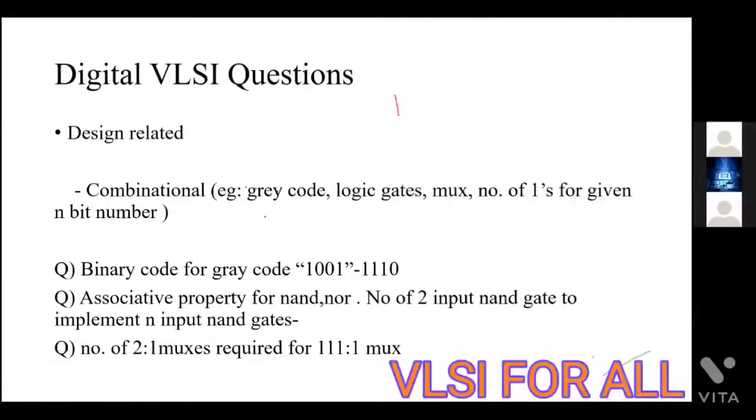So for NAND gate implementation, these are the 3 inputs. The circuit which I have drawn is for the 3 input AND gate using the 2 input AND gate. So here the associativity property holds, and because of that, you are able to implement the things without any additional excess gates. But coming to the implementation using NAND gate, the associativity property doesn't hold.